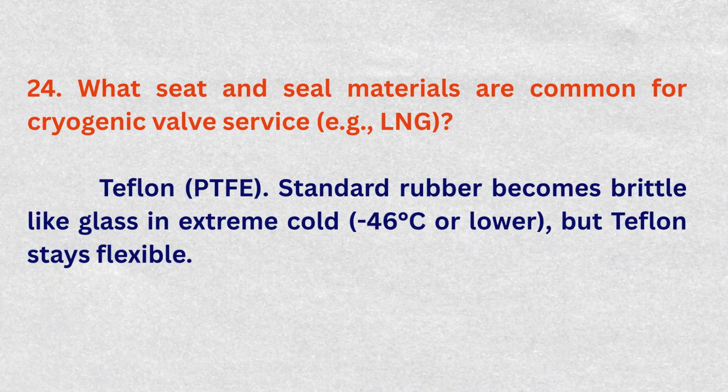What seat and seal materials are common for cryogenic valve service, for example LNG? Teflon, PTFE. Standard rubber becomes brittle like glass in extreme cold, minus 46 degrees Celsius or lower, but Teflon stays flexible.